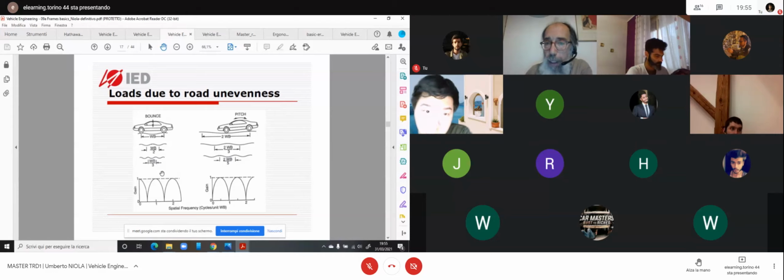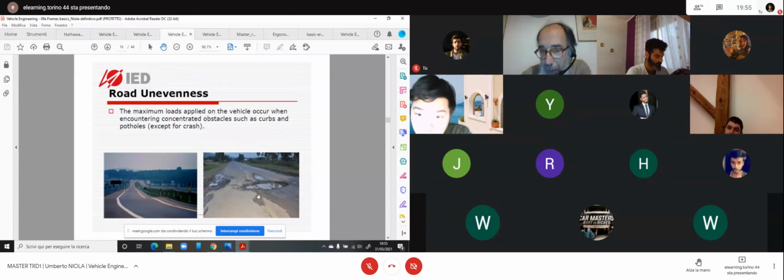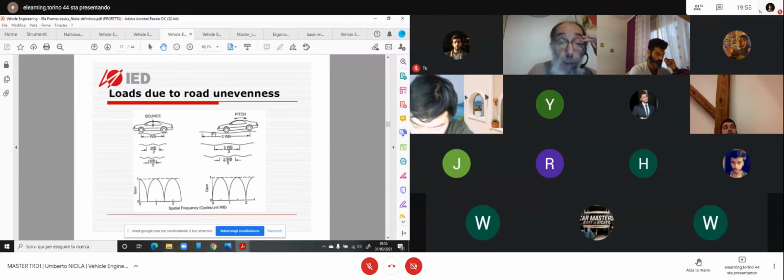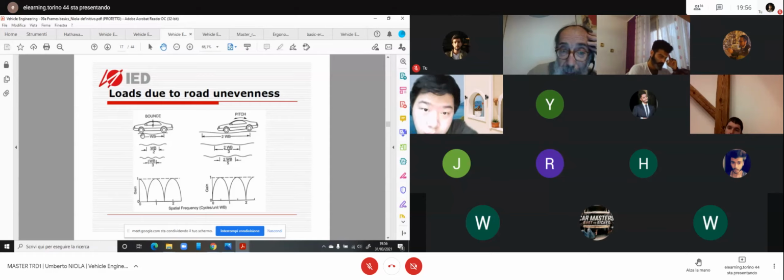The intention is to introduce the kind of solicitation they produce, because the peak for a very little time is concentrated on the suspension and wheel and the mountings. This other, on long waves, is introducing the problems due to this kind of proportion between the dimension of the car and the distance between two waves. So you have a parallel vertical movement, so no pitch of the body, if you have a distance which is corresponding to the entire proportion of the wheelbase.